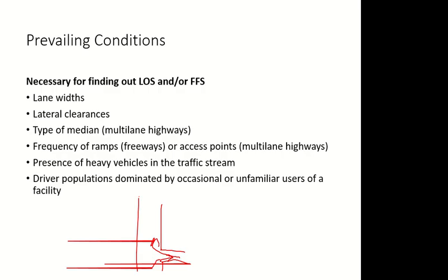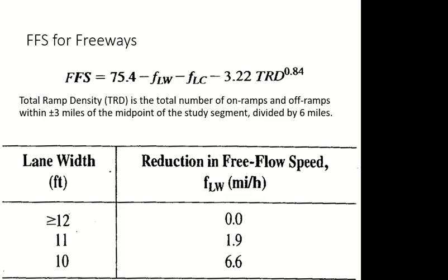So if you want to find out the free flow speed and level of service, you may need these things. This is the data which you should take from the highway, especially if free flow speed is not known. So what to do with the data? You have to put it in these equations.